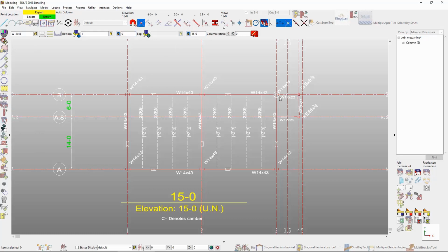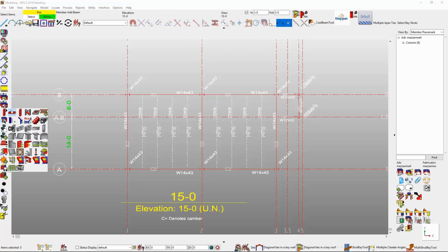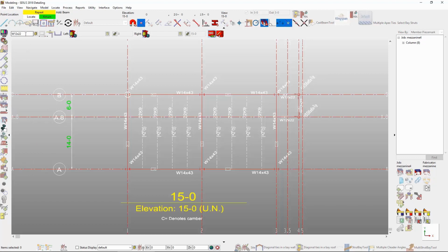If you have access to a BIM model that has been created in another software, you can import it in as an IFC, CIS2, or a DWG file. If you don't have access to a BIM model, you can import a 2D drawing to overlay as shown in this example. Oftentimes you are given a set of 2D drawings to build the model from.